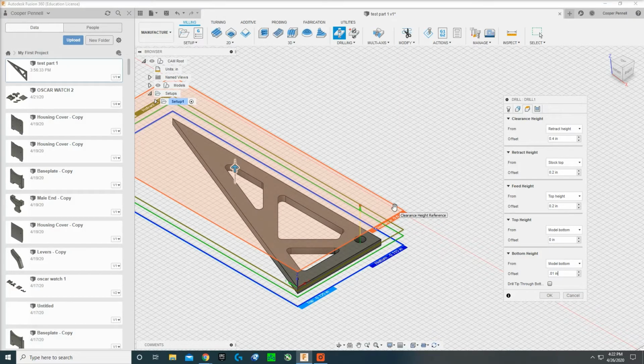However, say for example you home the machine 0.002 of an inch above that, which isn't very much. I've done it before. If we're not putting this offset of 1/100th of an inch down, it's only going to go down the 0.125 inches of the stock material. Because of that, you might be left with that 0.002 of an inch that you messed up when you're homing it. It's going to be on the bottom of the part, and you're not going to be drilled through the entirety of the part.